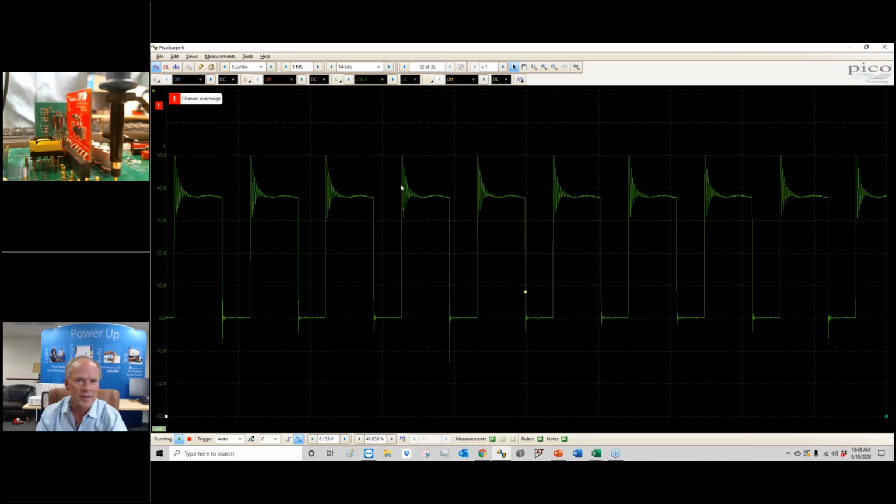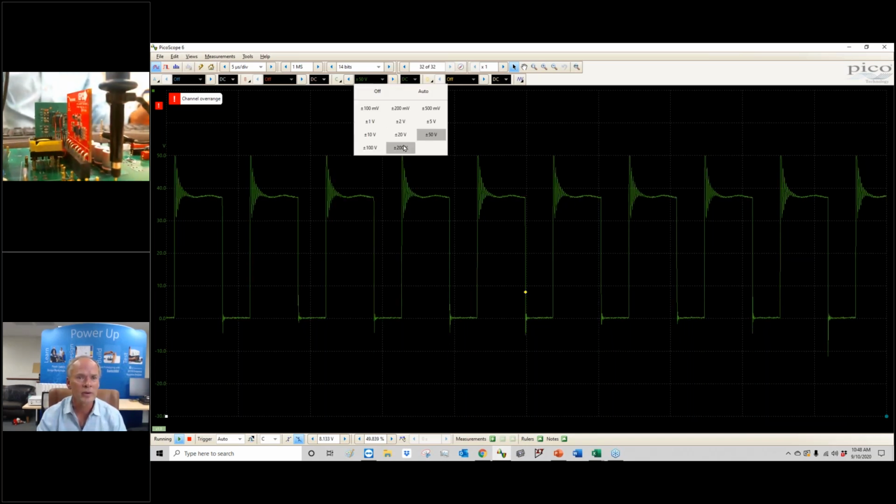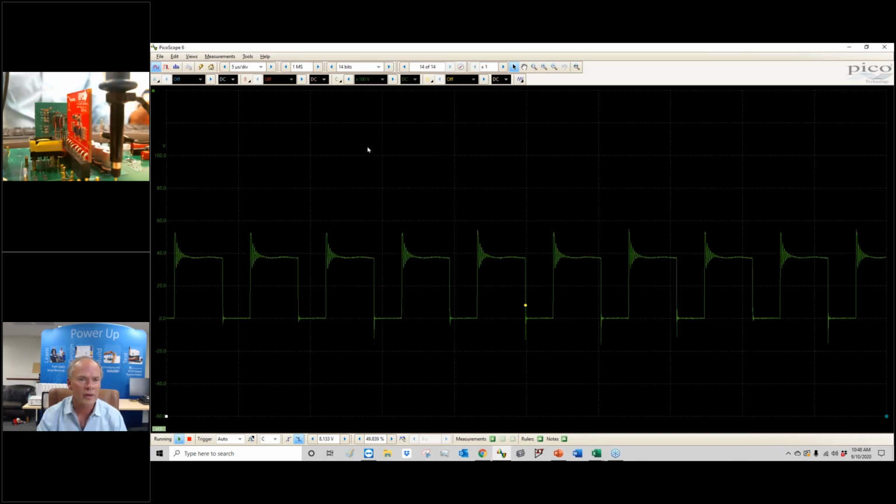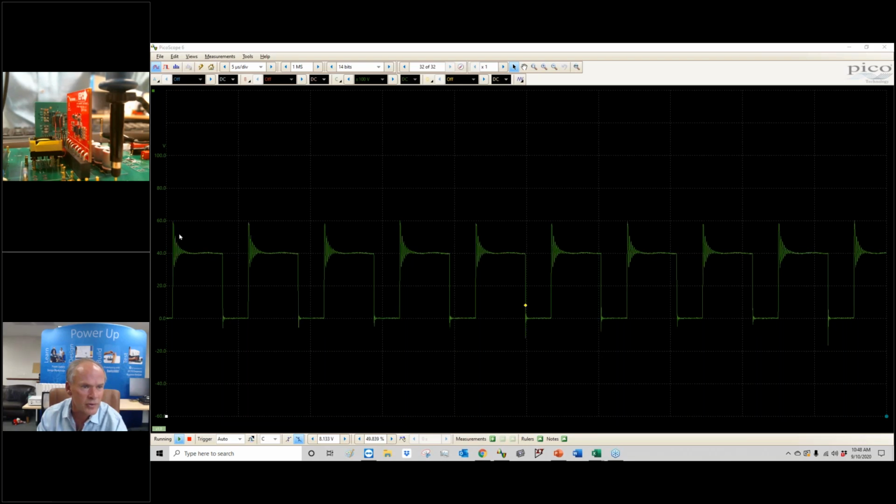Okay. Need a snubber on here. That's all part of our lab work when you come to our course. Plus or minus 100 volts here. The voltage rating of these FETs is 100 volts, so we're well below that. Because it's a clamped 2-switch forward, this voltage won't go above the input line, which is 60 volts here.